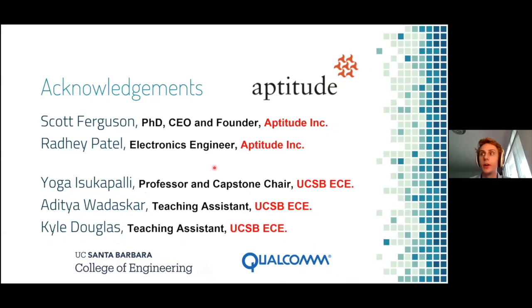There were a lot of parts, but one head scratcher was not understanding what a bootloader was, plugging in our finalized PCB board and not receiving any data back, and having to do a lot of Googling and figuring out how to get a bootloader flashed on a microprocessor that does not have those pins mapped out. It required a lot of tricky soldering with a microscope.